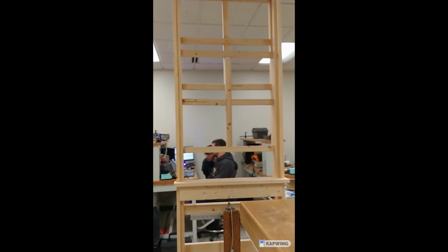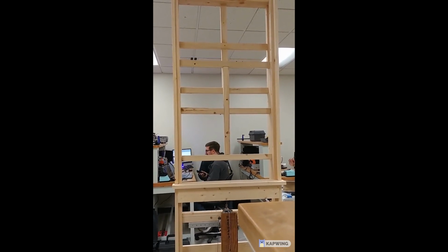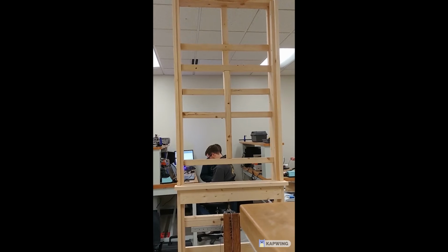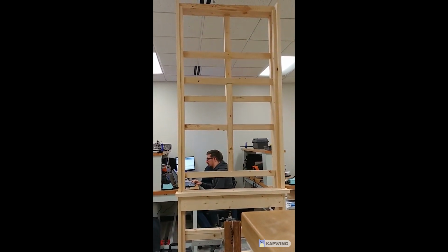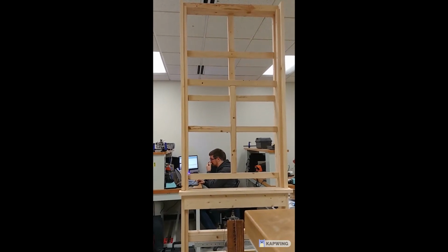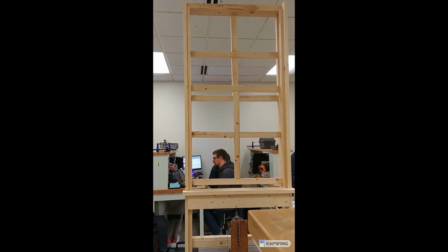Here, the set point of the system is being changed from the Particle Photon app. The set point was decreased, causing the feedback of the motor to become greater than the upper limit of the system. The forward output on the H-bridge turned on as a result and moved the window back into the accepted range. In this case, the window closed completely.